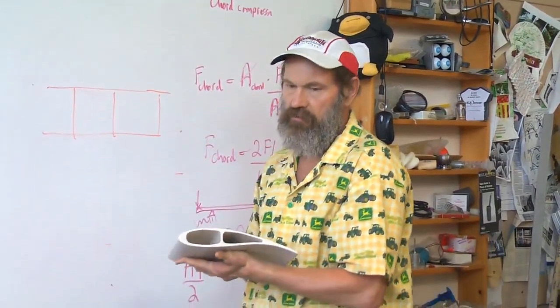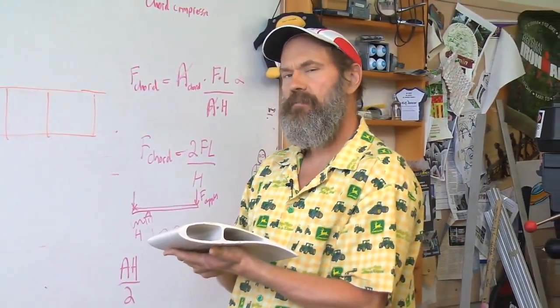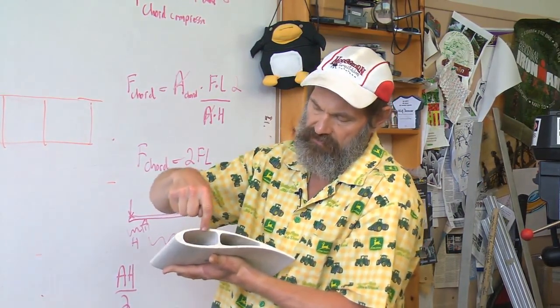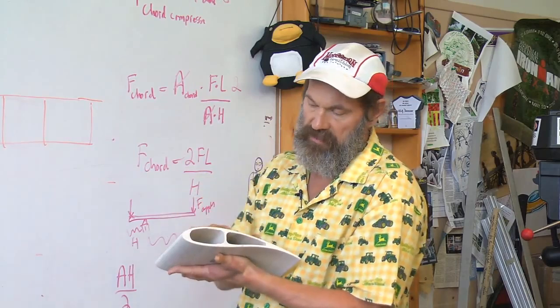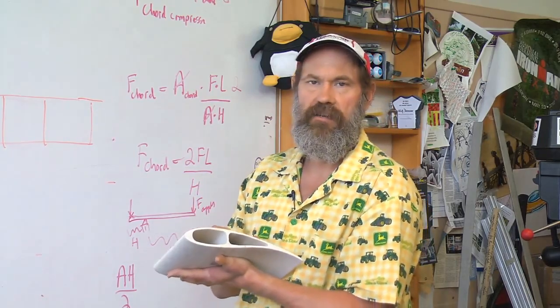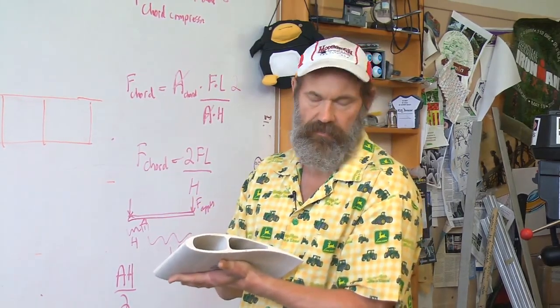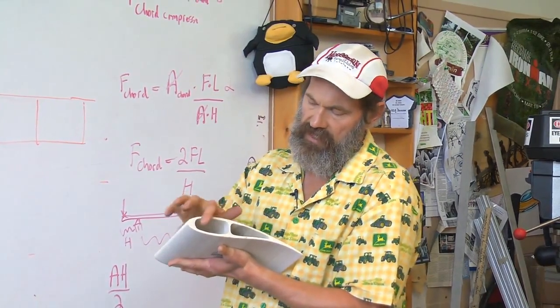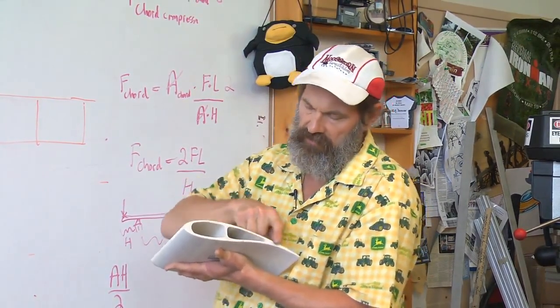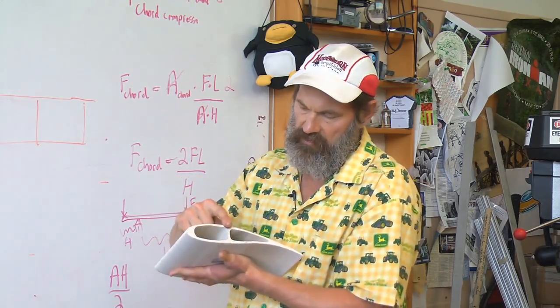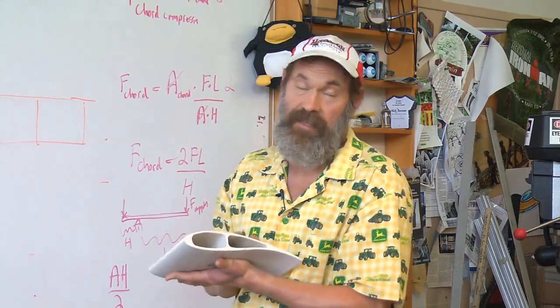So this gets back to: you should never generalize, because you might be wrong. If we added these on diagonals, it might be much stiffer. Do we need it to be that stiff? It might be much stronger, but do we need to be that strong? Versus, look how manufacturable this is, and I do have a triangle here anyway. This triangle automatically, by default, ends up supporting this rectangle, where adding diagonals does nothing for me at all, except add cost.